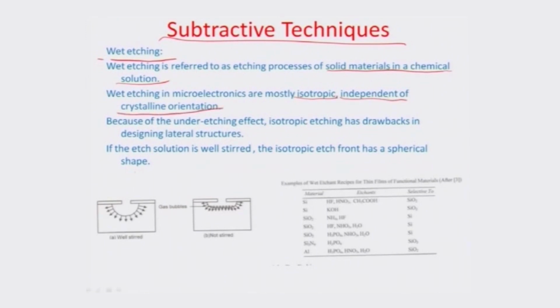So, let us say you are trying to etch the surface of silicon, and you have made a protective layer on the surface, which is not amenable to the etching process, or in other words does not corrode or etch out if you are using a certain etchant. This can form a sacrificial mask on top of the surface, and it exposes the silicon material underneath in this particular region. So, the etchant can go and eat away the material, and start etching in all the directions homogeneously, thus obtaining a hemispherical crater like this.